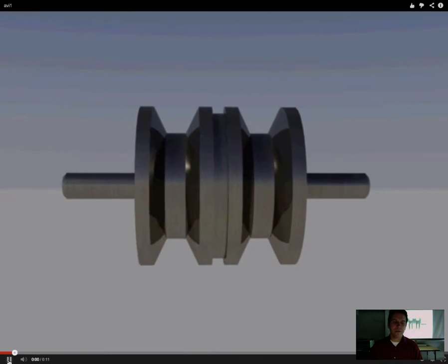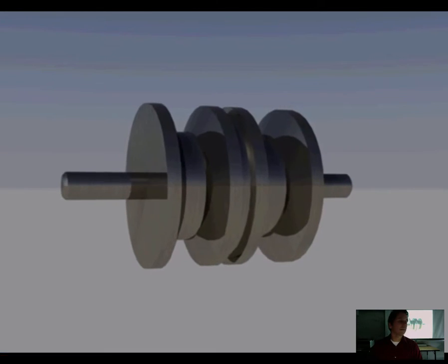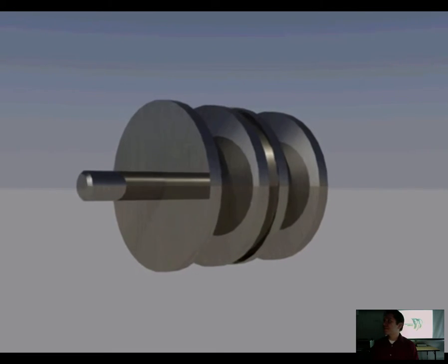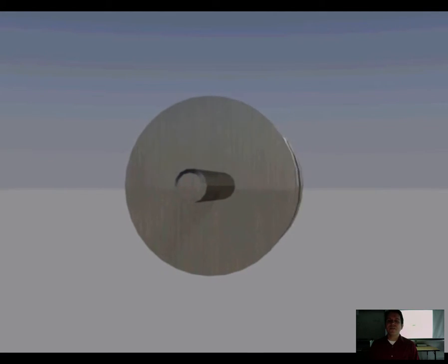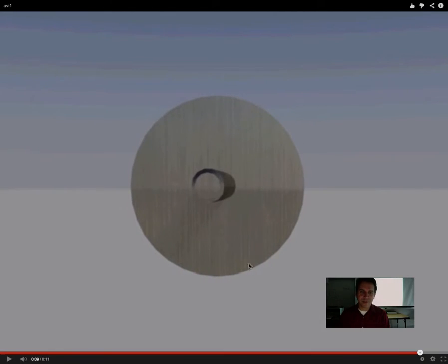Let's see if this will work at all. And then as I slowly rotate it, which you have to look at my screen, I guess this is working a little bit. So you can see these are our two different views. We have our front view. So anyway, when you look at it this way, all you'd see is this outer circle, this little inner circle, and since it's a chamfered edge here, a beveled edge, we would see these two circles together with this outer circle.